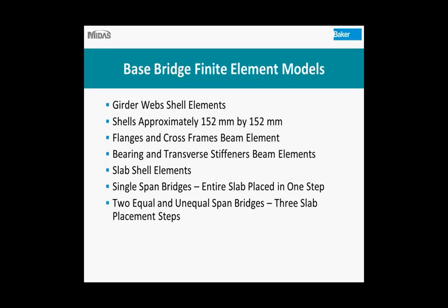So once we had all our base bridges designed, and I should say these weren't designed to realistically be built. They were designed, obviously, for use in a research program. We didn't go through and maximize our flange size, efficiency, etc. We picked the biggest flange size that would work so that the bridge wouldn't fail under live load, and used that for the entire section. But that was done for all of the bridges, so they were all over-designed in areas by the same amount.